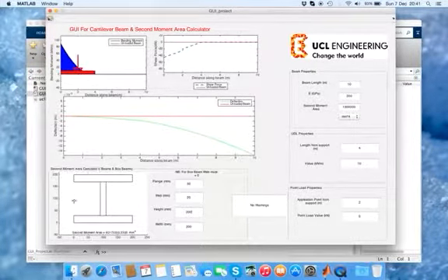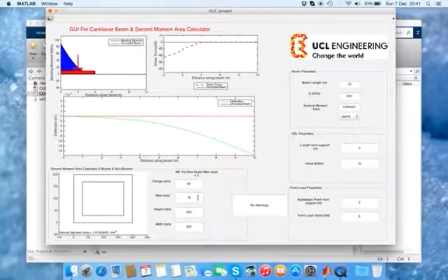And we can see here the beam has changed and the second moment area also in millimeters to the power 4. Now this can also be changed into a box beam by applying the fact that the web must equal 0. So the box beam has a flange, in this case, and web of 30 and a height of 200 with a width of 200.